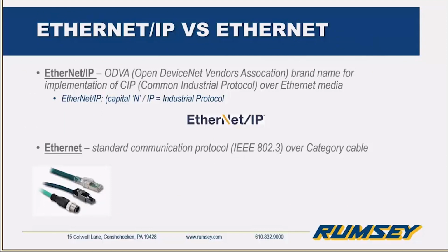So as a former IT professional, when I first heard the term Ethernet IP, I was immediately dismissive, and that's not a thing. This is just because it was never explained what Ethernet IP was. Specifically, Ethernet IP with the big N/IP, it's the branded term for Common Industrial Protocol, or CIP, transmitted via the media of Ethernet. The IP actually stands, in this case, for Industrial Protocol, which is unfortunate because that also stands for Internet Protocol in IT-based computer science, hence the confusion.